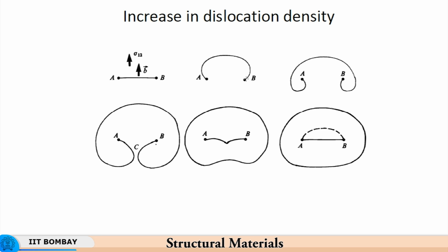So now we go to the reasons why that 5% energy is stored. What stores that energy? Yes, the dissipation in the form of heat is understandable, because usually most of the energy gets dissipated in the form of heat. But then the 5% energy is stored in what form? It is in the form of increased dislocation density. So if you have a certain number of dislocations per cubic meter or per unit volume of the material, with deformation the quantity of these dislocations continues to increase, and this multiplication of dislocations takes place in the following manner.